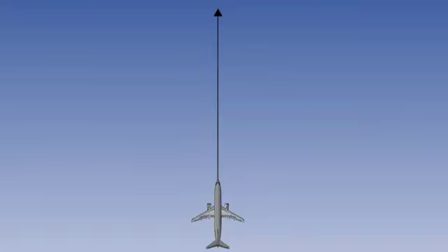Apart from leveling, there is also the heading output to consider. Horizontal direction is called azimuth, so this error is called initial azimuth misalignment. Gyro compassing usually results in an initial alignment accuracy of about 0.1 of a degree. This is very accurate compared with a gyromagnetic flux valve heading, but even 1/10th of a degree introduces appreciable errors.